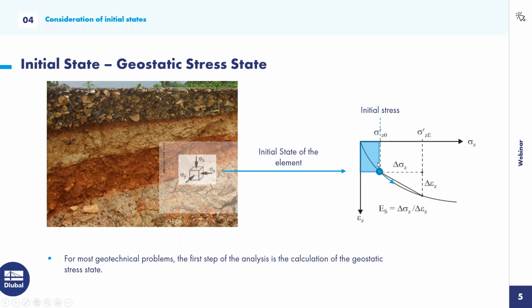This curve here is quite important. We start the calculation at this point. We consider the initial stress caused by the self-weight of the soil. And what I have to say, only internal values are transferred in the initial state, such as stresses, strains, stiffnesses. Both the initial stiffness and the stresses are considered. And regarding the stresses, it's important to have the total stresses in the structural system, because only then the right stiffness is used. As I mentioned, we start the calculation here, and that's the end state here.